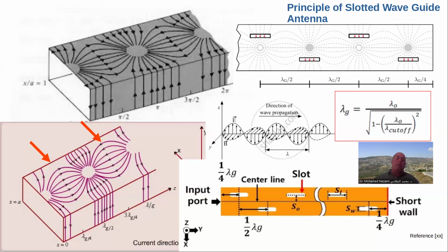Now, that may not be acceptable to some communication systems, such as accurate high-resolution radars. So what you want to do is taper down these side lobes, and we do that with windowing or taper. So that's why we resort to designing the placement of these slots from the center line here.